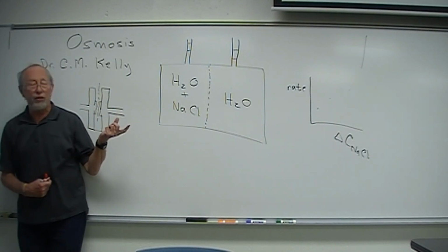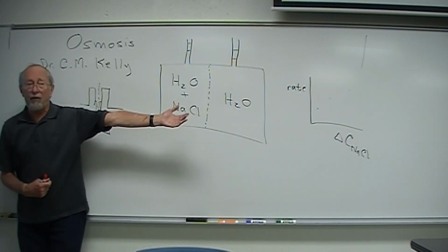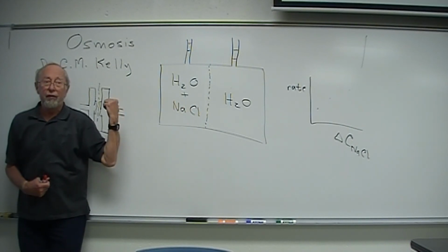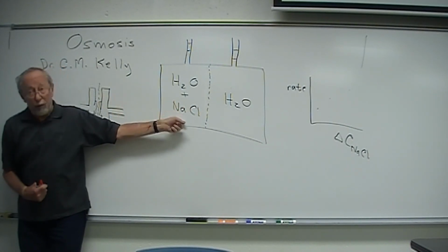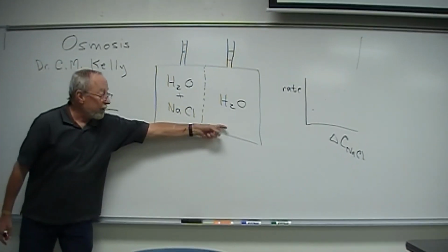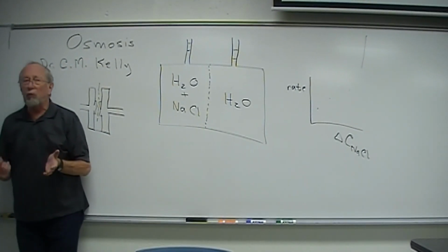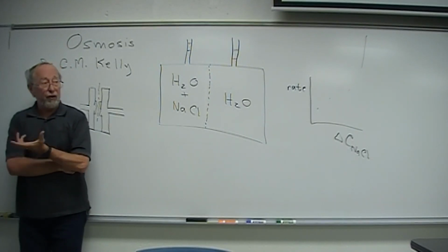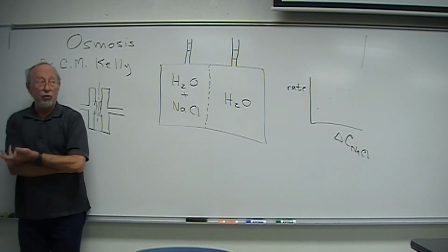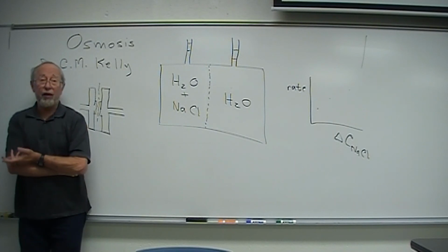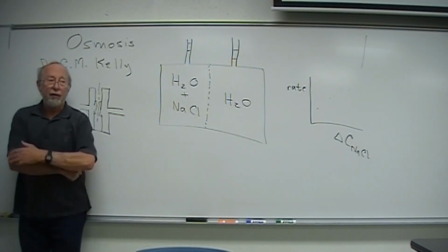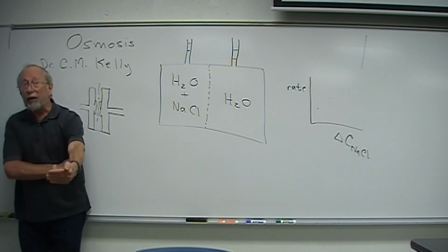The only difference is you adjust the driving force so that it forces the water to go that way instead of coming this way. The way to do that physically is to really pressurize this side compared to that side, and so you've got to design equipment which can handle the pressures, which is big enough to provide a reasonable amount of water so it's useful for something, and the transfer rate is high enough through the membrane that you can make water quickly.